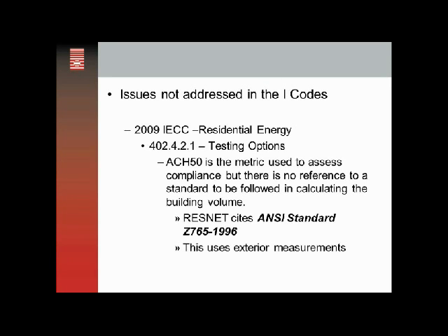The Army Corps of Engineers / Air Barrier Association of America test protocol also reports the metric in CFM per square foot of surface area of envelope, that surface area being defined as the six-sided box: the slab, the four walls, and whatever constitutes the lid or the ceiling of the building, whatever separates the building interior from the exterior.